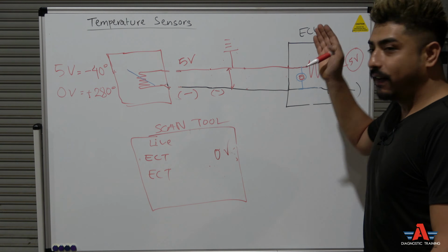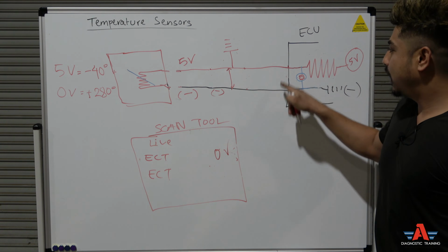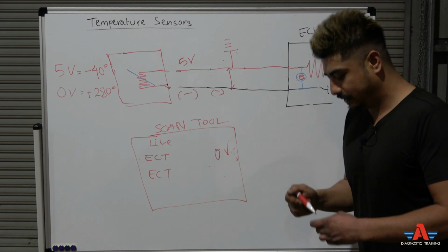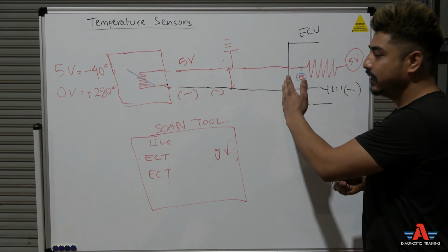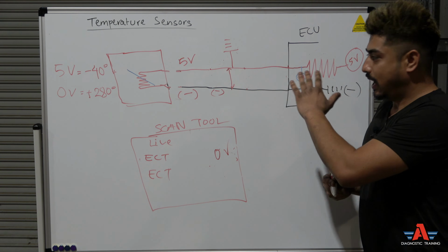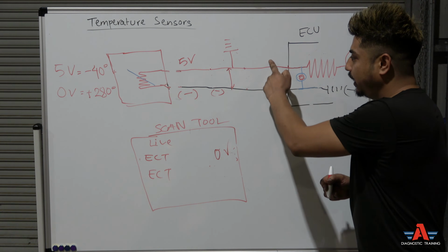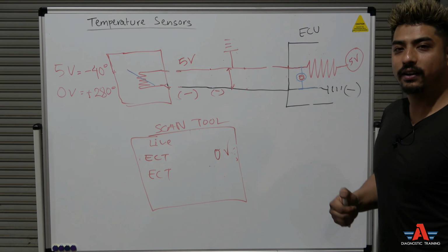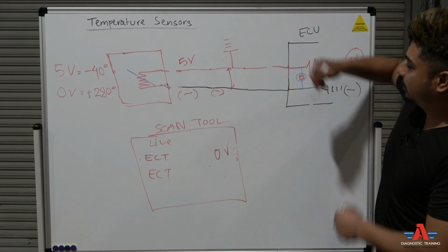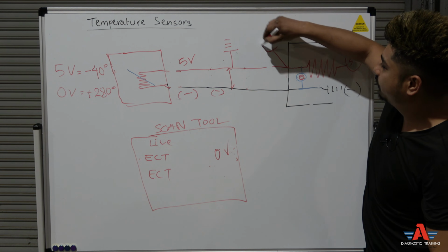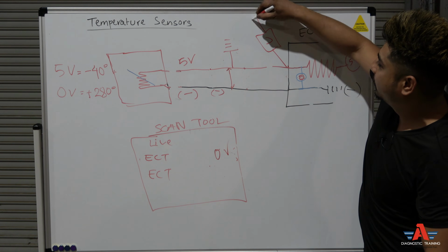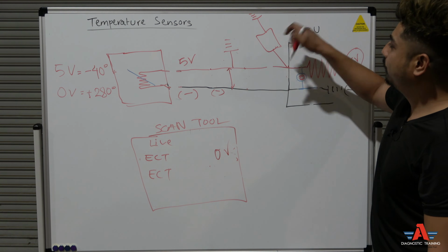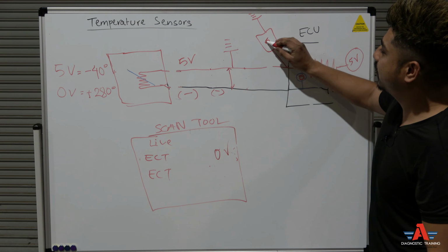to the computer, find the wiring diagram, and look at which pins are the 2 wires for my coolant temperature sensor. Go to the computer, find the wires. Now at the computer, I would cut this wire just near the computer and check the voltage here with your multimeter, to ground obviously. As soon as you cut that wire, did that jump to 5 volt?